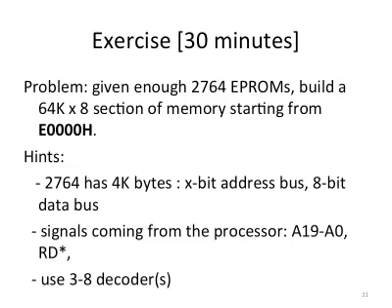Now here I want to give you an exercise. The problem description is as follows. Suppose you will be given enough 2764 EPROMs, and we want to build a 64K by 8 section of memory starting from this particular address. Assume the number of address bits is 20 in total.